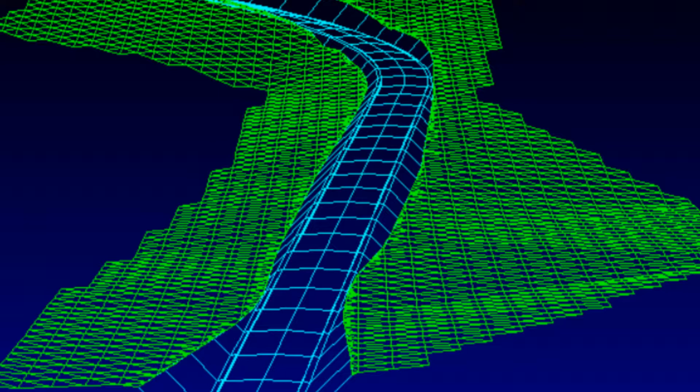These contours are also used in calculating the earthwork required for roads and railways. You can see the green pattern in the figure which represents the ground terrain conditions where we need to engineer it in order to fulfill our road requirements. Some part of the road is filled in order to make the elevation of our road. Some part of the earth is cut in order to maintain our road level. So these all come under a subject called leveling.